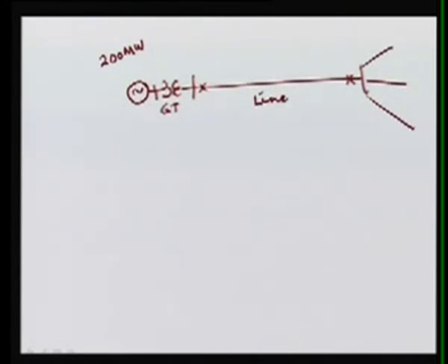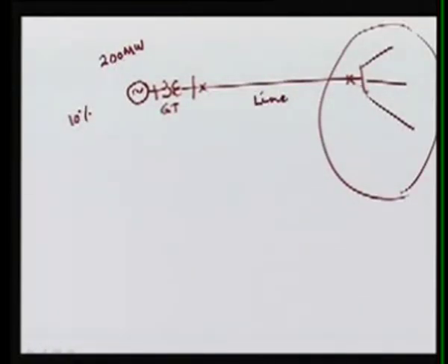Now, if you want to connect this generator with this whole system, which is a big system that is operating, what happens? Normally, we charge this line without loading it, because initially this generator is operating at minimum power, normally only 10% is allowed. If it is a thermal power station, it requires 10% of its rated capacity, so it actually requires some power. So this generator is initially running at a very small load. We cannot load it, as we do not know how much load is required. So to connect, this line is normally open, and then we connect it here at the circuit breaker.